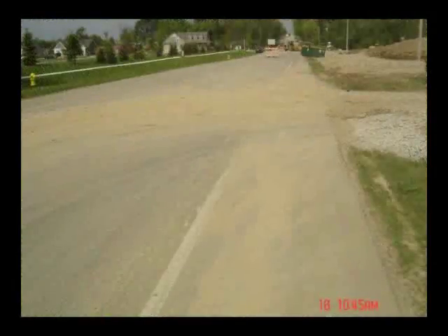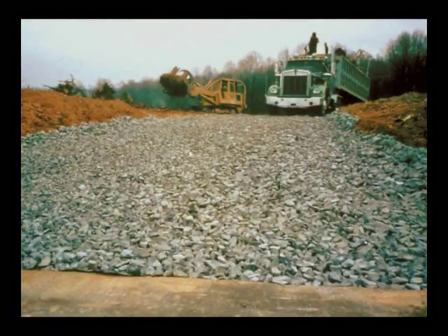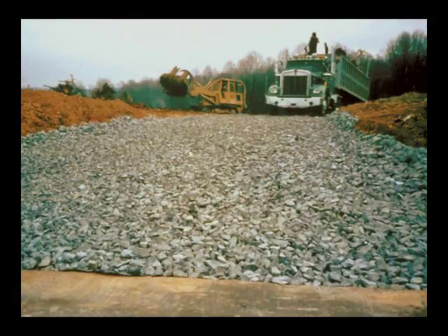To prevent sediment from being carried out of construction sites in the tires of vehicles, rock construction exits can be implemented as a temporary sediment control measure. Rock construction exits should be installed prior to the commencement of construction activities. At all designated exit areas, filter fabric should be placed on the soil surface and covered with a bed of 4 to 8 inch diameter crushed rock or stone. The exit should be at least 50 feet in length and wide enough to accommodate construction vehicles.